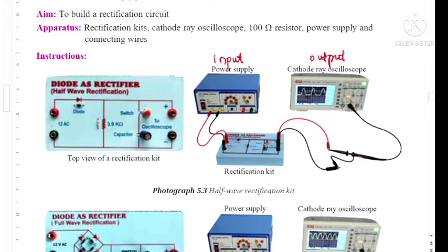As you know that for input is alternating current, direction of alternating current keep changing every half cycle, positive, negative, and so on. If you look at the output here, the negative part is missing. So this one you can see direction of current is flowing in one direction. The output is DC.